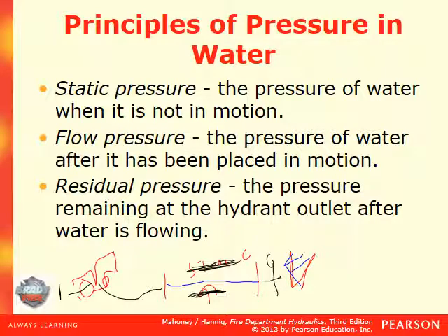And that is our flow pressure. Now we go back over here to our hydrant. The water that's left in the hydrant down here that's not actively being used will exert pressure, and that is known as your residual pressure.